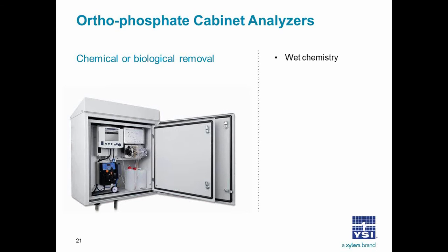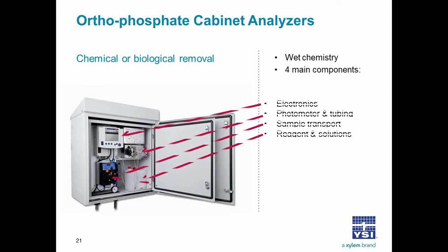These all rely on wet chemistry, and there are four main components to an analyzer: electronics, photometer with tubing, sample transport, and of course reagents and solutions.